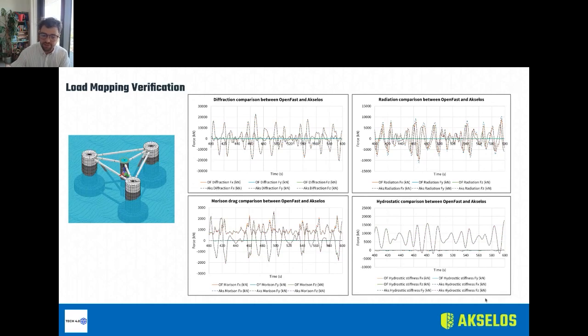And this is information that's continuously generated by the ILSA toolchain, and something that the user can check at any time. So if necessary, if there's something wrong, the user can know before having to run expensive FEA simulations. The user can know whether to turn off or continue the simulation. And what we recommend doing, how we see this workflow actually unfolding, is that there's a first batch of, let's say, test simulations that can be used to precisely analyze this output and make sure that everything works. And once that's the case, the user can just throw in all of the load cases that he needs to run.